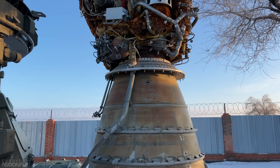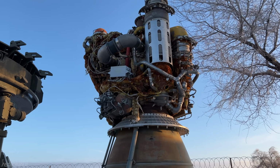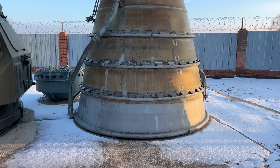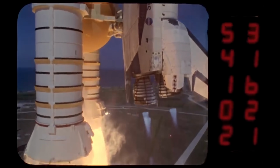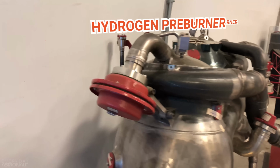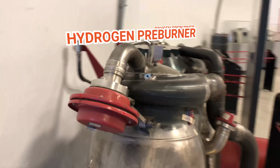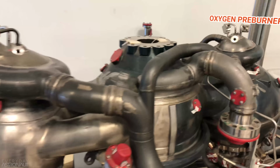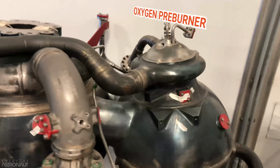And although single shaft hydrolox fuel-rich closed-cycle engines have been made, like the Soviet Union's RD-0120 at the heart of their Energia booster, the US went with a different solution that raised its own set of problems. Their design for the RS-25 called for dual preburners on two different shafts, both fuel-rich. One preburner would power the fuel pumps, and the other would power the oxygen pumps.